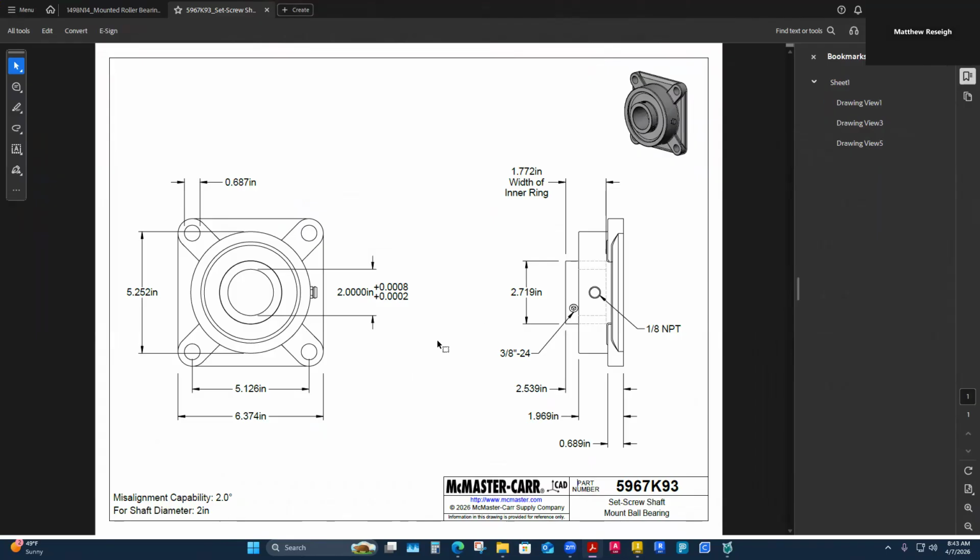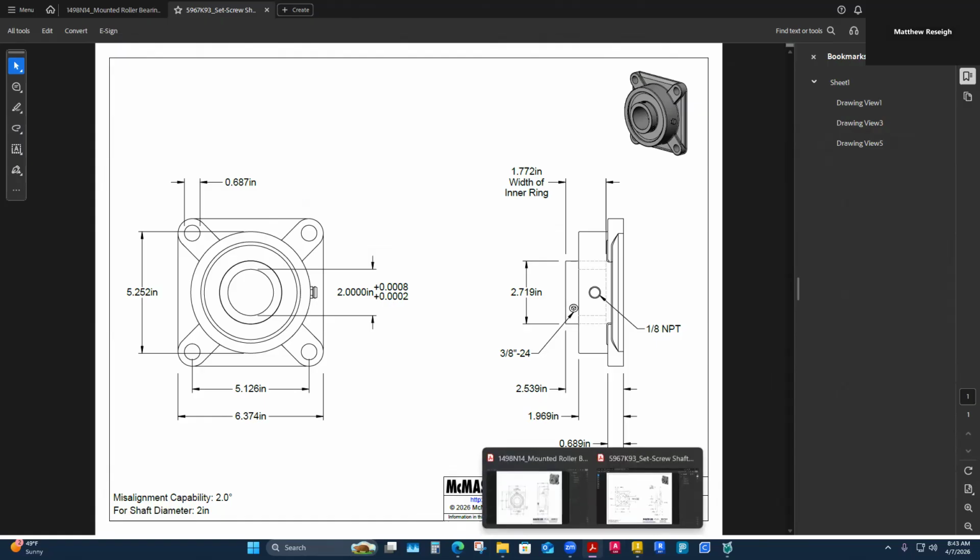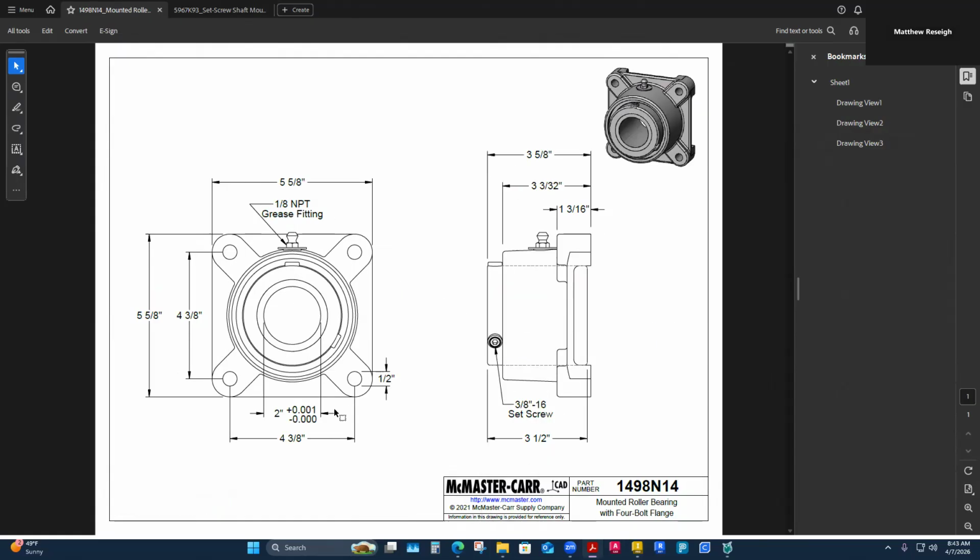So I think what I determined is we've made ours match this. 687. Well, I could check my solid. I think we actually spent the work on the solid, figuring out what we were threading at. I think I did 5/8 here. Is that what I did? Or did I do half inch maybe, and then I'd have a pretty sloppy fit. Here I know they're half-inch holes, and so I use 7/16. I remember that for sure. It's a little bit of an oddball size, but it's readily available usually on shelves. 3/8, 7/16, half inch, pretty common size. So I think I use 7/16 threads for this one.